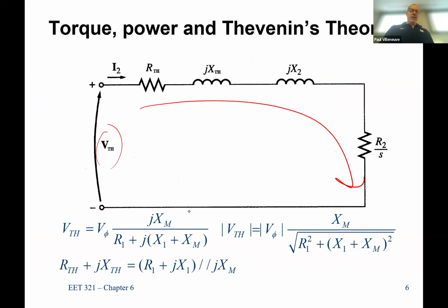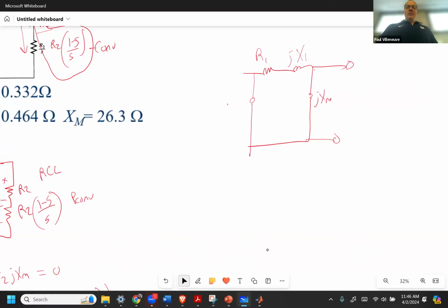So that's why we have this equation. Well, I should say this equation, they're in parallel. The voltage is still pretty easy to find, right? Because if this is not a short, if this is an actual power supply, and I'm trying to get the voltage over here, just voltage divider, isn't it?